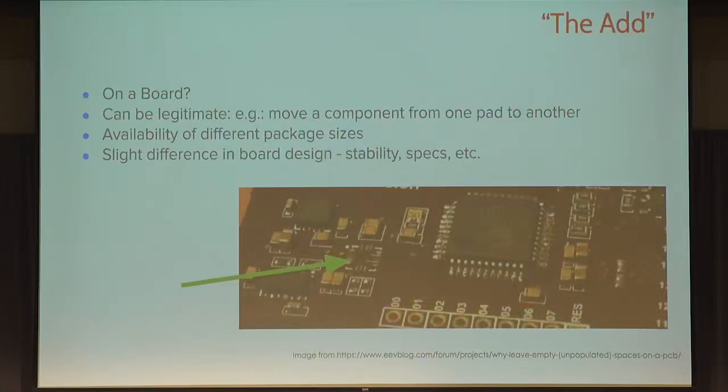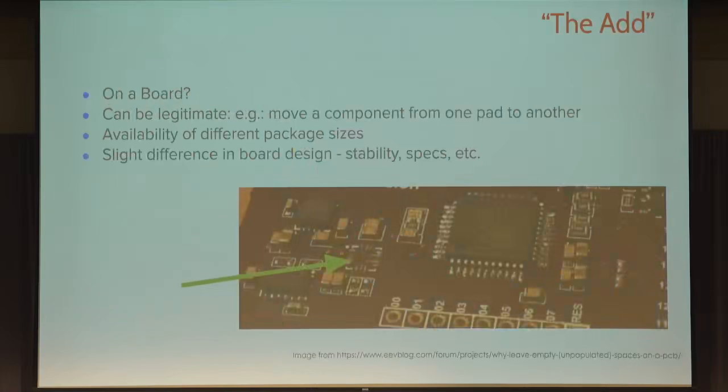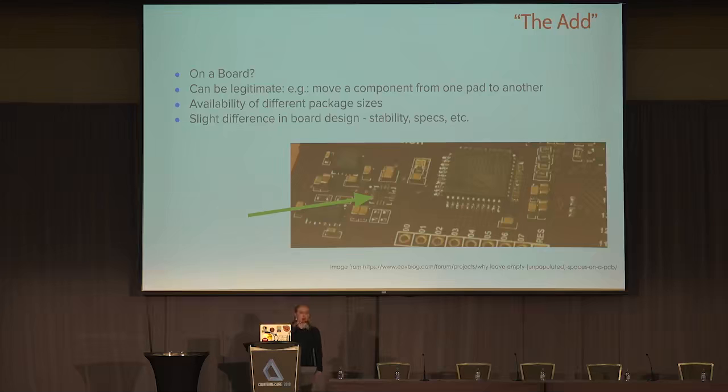All right, so the add is a different type of technique, right? So you have the sandwich, you have the add. The add would be what the Supermicro case was alleged to be. It'd be an addition to the board. However, the issue with this is, of course, that it can be a legitimate add, right? You can move one component from one pattern to the other to save costs. You would replace a component with a different one that has similar functionality that also reduces costs. There's different package sizes available for certain things. And depending on logistics of that manufacturing plant, only certain ones might be in stock.